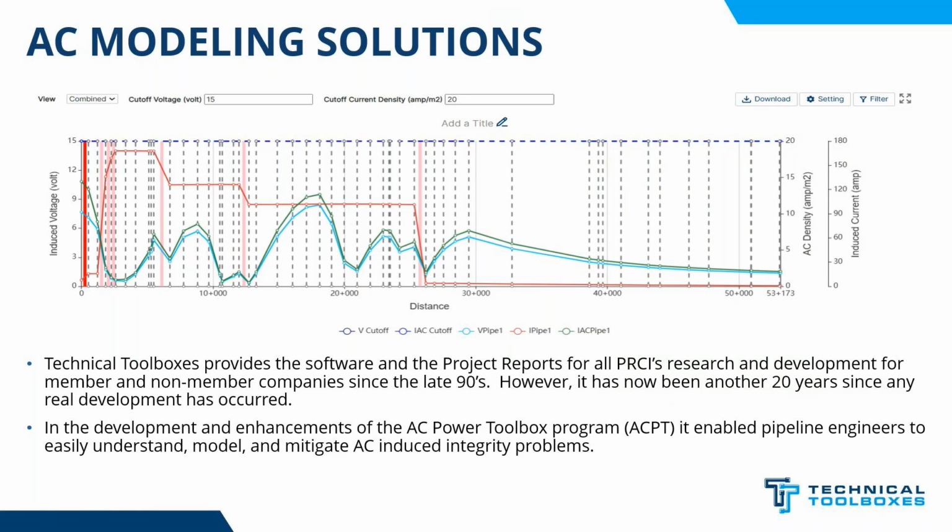Okay, so what we have here, and we're going to get into this in a little bit, is a graph of what we just modeled. And it didn't take long to model this. I added some mitigation in here. This red line happens to be a discrete anode near an isolating flange, and the rest of them are distributed anode systems, to bring this down.